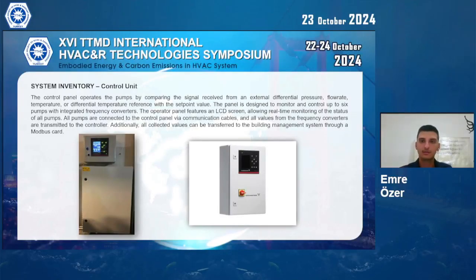The panel is designed to monitor and control pumps with integrated frequency converters, and it can also monitor and transmit these frequency converter values to the controller. Additionally, all collected values can be transferred to the building management systems via Modbus cards.